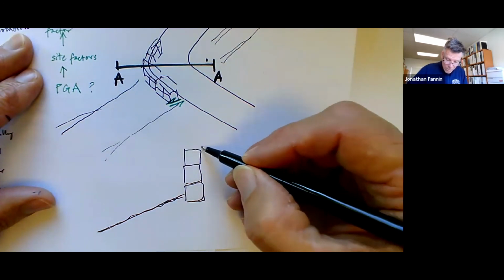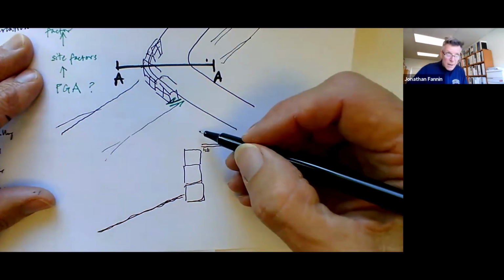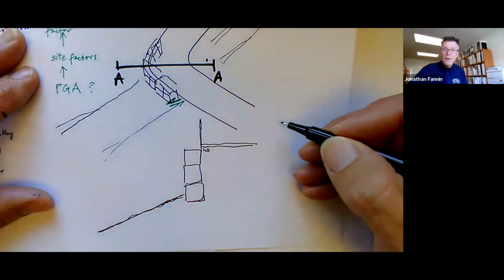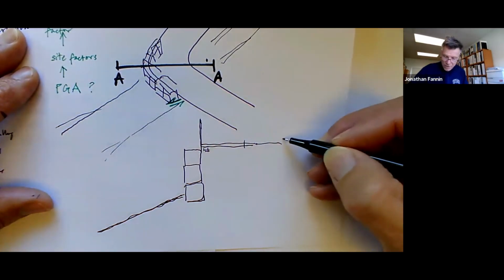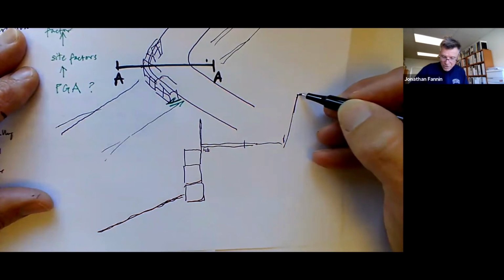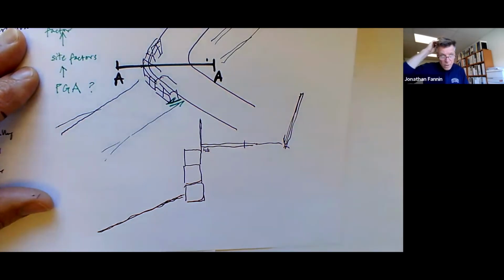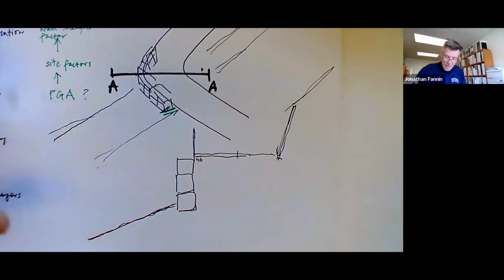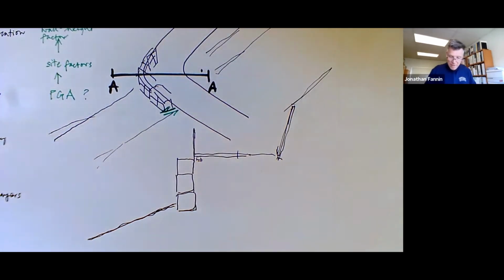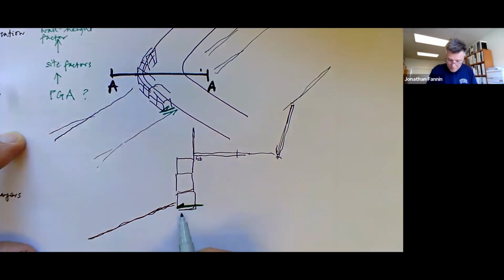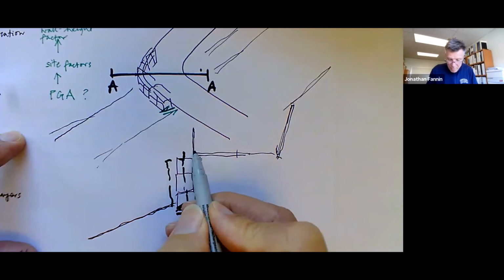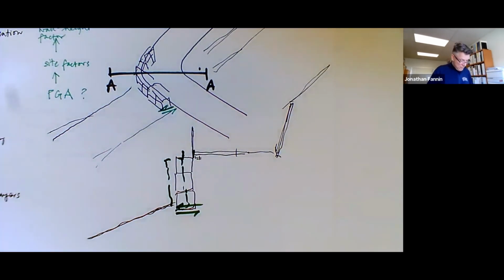We've got drainage provisions, we've got pavement and a fence. And then 2 lanes of highway, and actually another retaining structure here. If memory serves me correctly, they were timber pile, and then the ground going back up again, and these displaced out, didn't collapse, but displaced out by a distance here, perhaps of 25 centimeters to 50 centimeters.